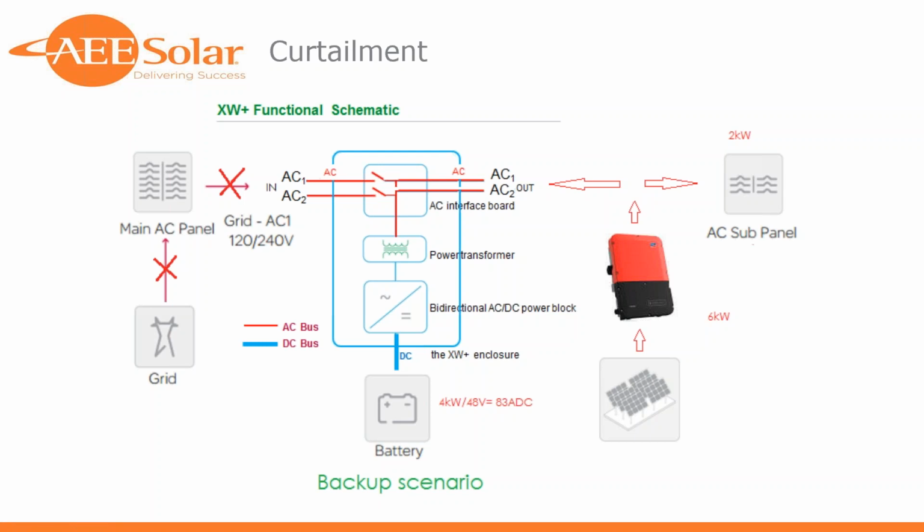And I say it's not a very elegant way to do it because this being a PV inverter, it still has to respect the rules of 1741. When the grid requalifies, it's got to count up 5 minutes and then start producing power again. So it's a very lumpy way of providing wattage to this application. The other thing you typically see in these AC coupled applications is the battery is usually not large enough to control those uncontrolled charge currents and to ride through the 5+ minutes of startup again.